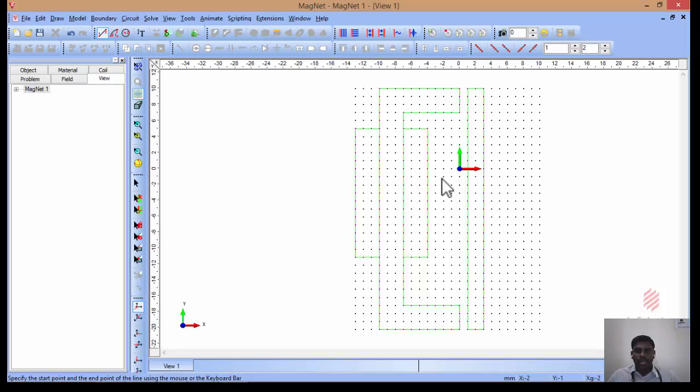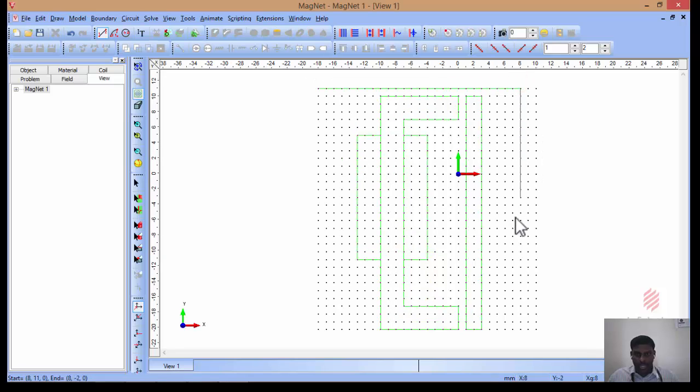So now we modeled the actuator with a static part as well as a rotating part. For electromechanical energy conversion to take place, we need to model air. If you want to model air, we need to have a boundary, so we need to draw a boundary over this. It's an optional dimension in a numerical technique.